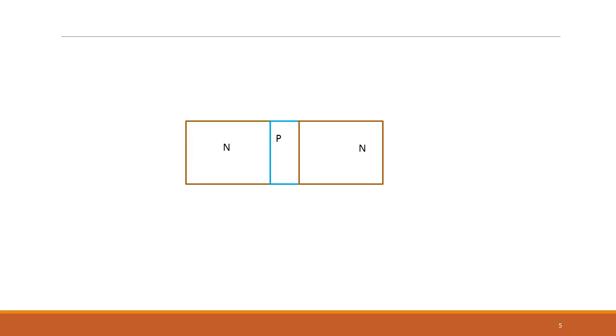Now, we saw the bipolar transistor, NPN we saw, PNP we saw. Instead of PNP, we'll talk about an NPN transistor now. The base is the p-type material, and then you make the emitter n-type and the collector n-type, and you forward bias the base-emitter junction, which is this.